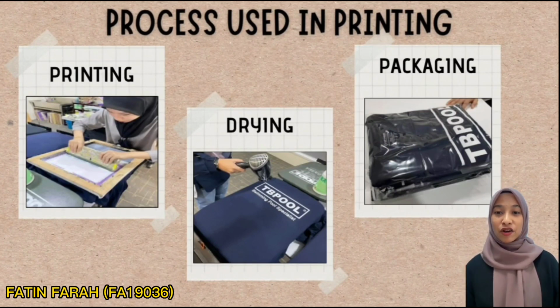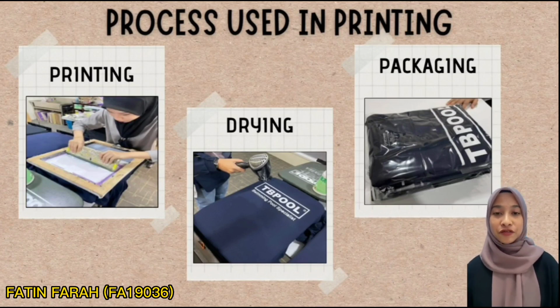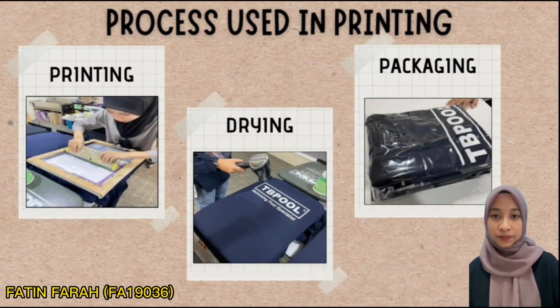Lay a thick bit of ink above the art, extended past both ends. Ensure to add extra ink above the flash area to be printed if needed. Use both hands to evenly pull the squeegee fully across the screen. Remove the screen and wash out all the ink before it dries.